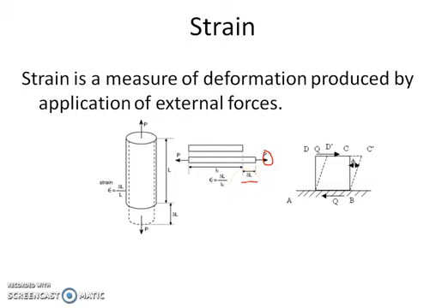This change in length per unit length is nothing but the strain epsilon. So the length of the member is L naught, whereas epsilon is the strain, which is given by delta L by L naught. Delta L is the change in length and L naught is its original length. So this strain is called a linear strain. Similarly, if there is a compression force, there will be reduction in the length of the member, and here the change in length is the reduction in the length of the member. Change in length towards original length is again the strain, and it is called compressive strain.